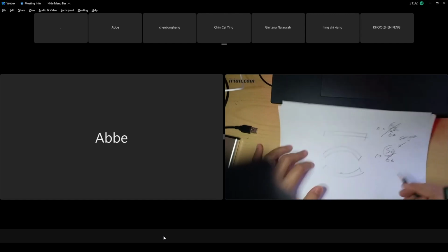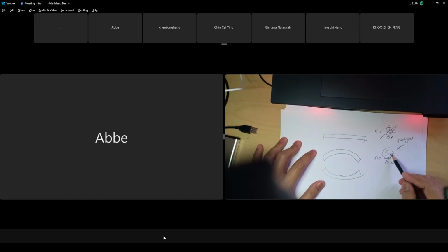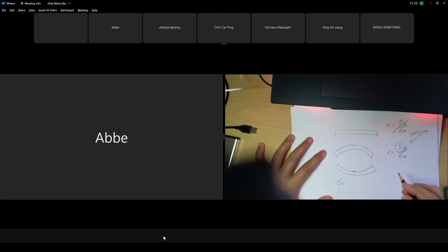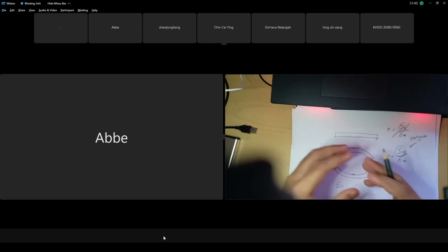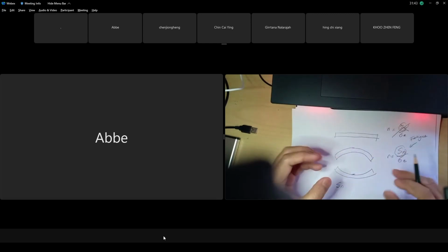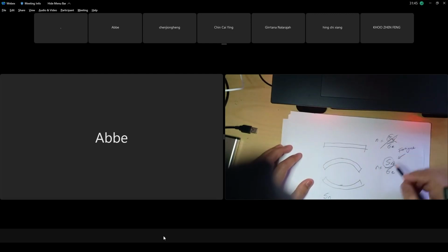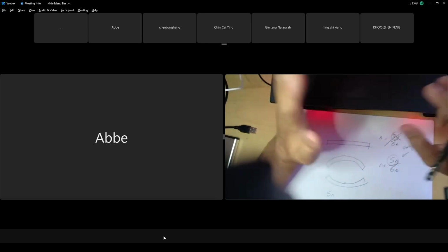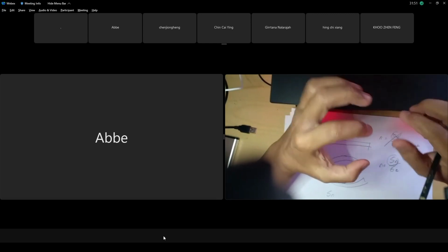So you can no longer use SY. Endurance limit, you will calculate later. What is endurance limit? It is what the material, the component, can endure. The endurance limit is not yield strength. It's lower than your yield strength because the loading is fatigue. The loading is fluctuating, so your material has already weakened.